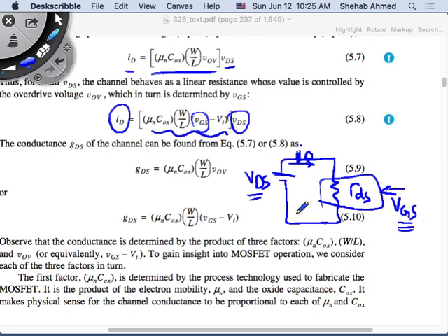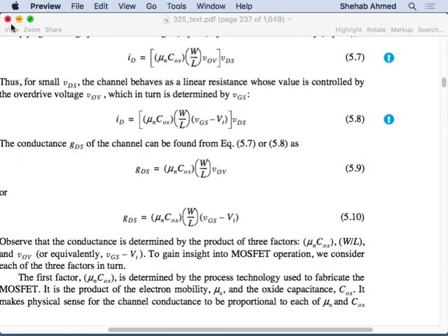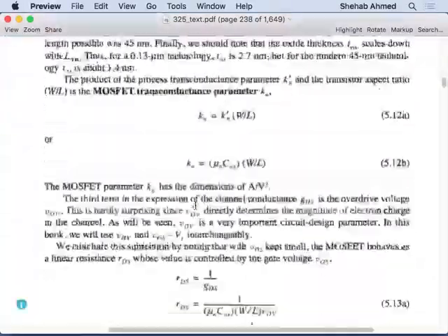Next class we'll see that if I fix the value of resistance, how would I draw the relationship between I and V? If this value of resistance is fixed, say 5 ohms, it's a straight line. I versus V is a straight line. The slope of this line is delta I over delta V, which is 1 over R. And that's what we have on the next slide.